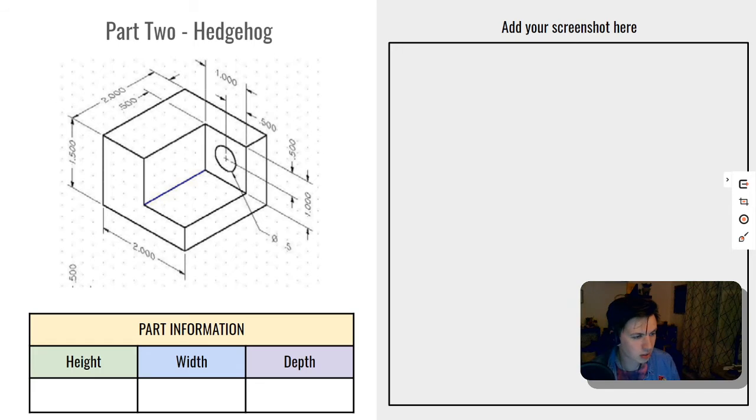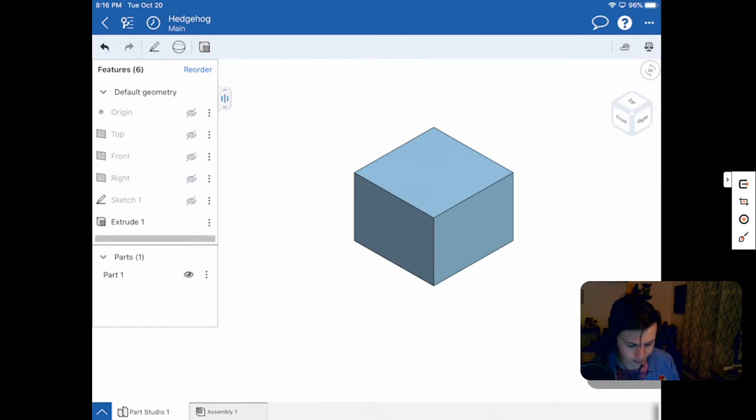So when I look over here, I want to get this smaller cube subtracted out of here. So what it looks like is that this cube, if I'm reading the dimensions correctly, is 1 inch by 1 inch, and it extrudes a depth of 1.5. You see the difference between 2 and 0.5 over here. We have a difference of 1.5. So we extrude back a 1 by 1 cube, a distance of 1.5. All right, let's go back into our drawing.